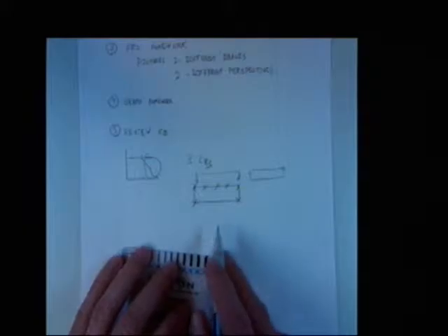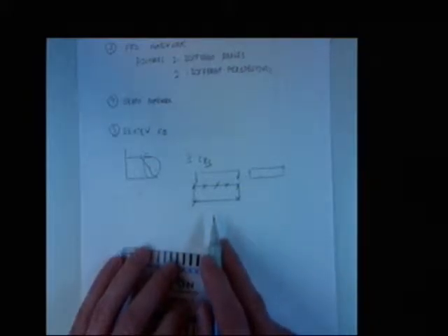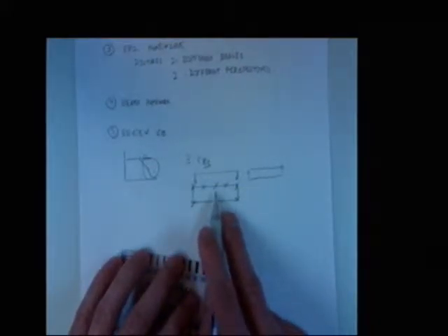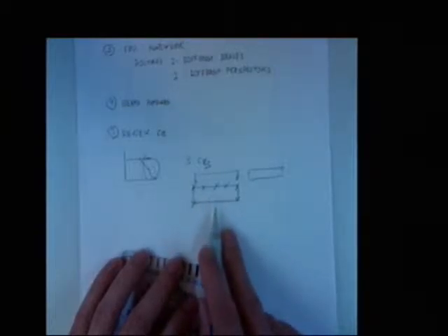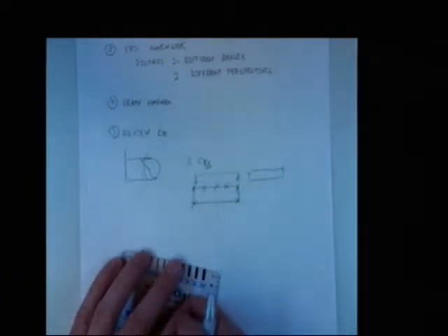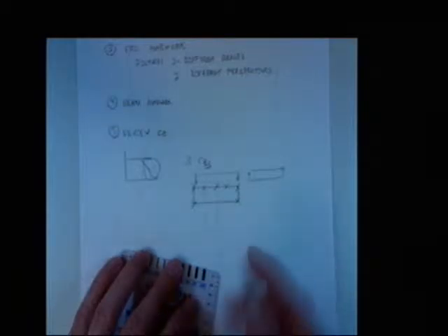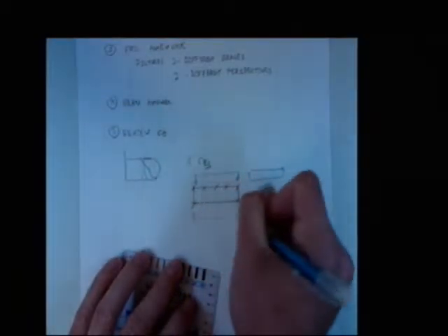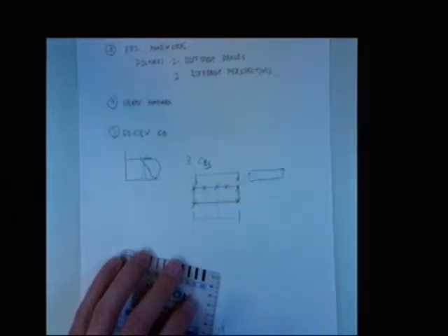Yeah, I think you said the keyword, brace. A lot of people might think about this structure and say that it is braced. And they might say that L sub B is 0, or something very small. Right? And what did we learn the real value for L sub B was? Entire length. Okay, that's number 1.